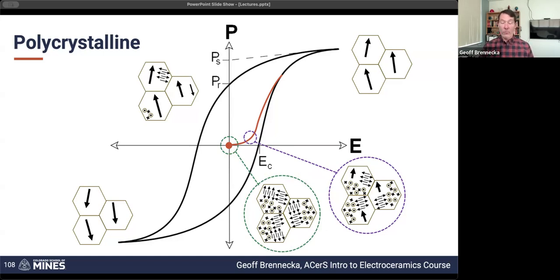And so why does this matter? Well, the very simple reason is this remanence, you've got two completely identical inverted states. You can think of that as, for example, the ones and zeros of computer memory. There are ferroelectric memories that are based on that. You can also, this is how we break the symmetry of the polycrystalline ceramic to create a bulk ceramic piezoelectric.